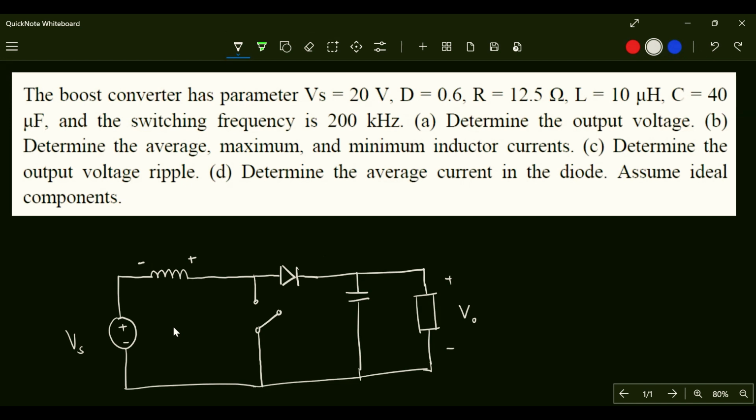So if you look at this, the diode now is in forward bias, isn't it? Because it's going to the positive terminal of both the voltage source as well as the inductor. Remember the inductor this time around is acting like a voltage source. It is charged up, it's storing some charge, so it has voltage across it, right? So this inductor and this voltage source are in series, and both of them are trying to send the current in the same direction, right? So you have positive terminal here, negative terminal here. Remember the current moves from high potential to low potential, right? And this inductor also is behaving the same way, sending current in the same direction.